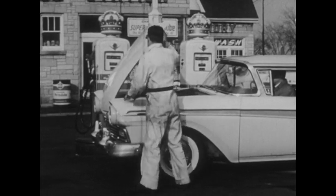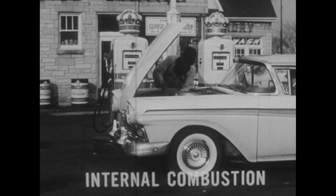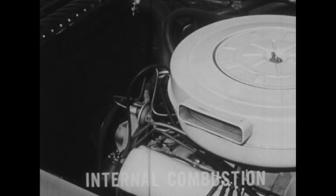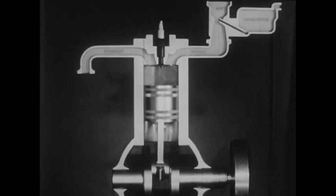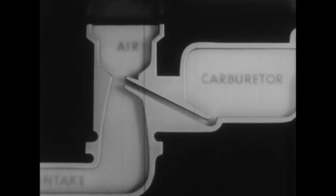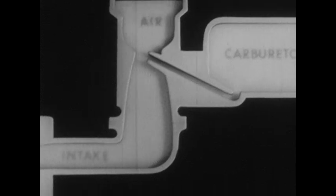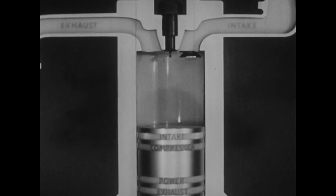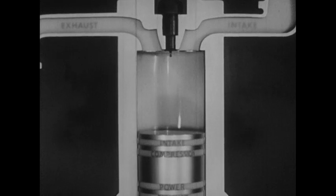The engine of the automobile is a good example of a reciprocating internal combustion engine. Fuel is burned inside the cylinders of the automobile engine. This cutaway model of a single cylinder will help us see how it uses heat energy. In the carburetor, air is mixed with fuel, forming a fine spray, which passes through an intake manifold to the cylinder. In the cylinder, the piston moves through what is called a four-stroke cycle.